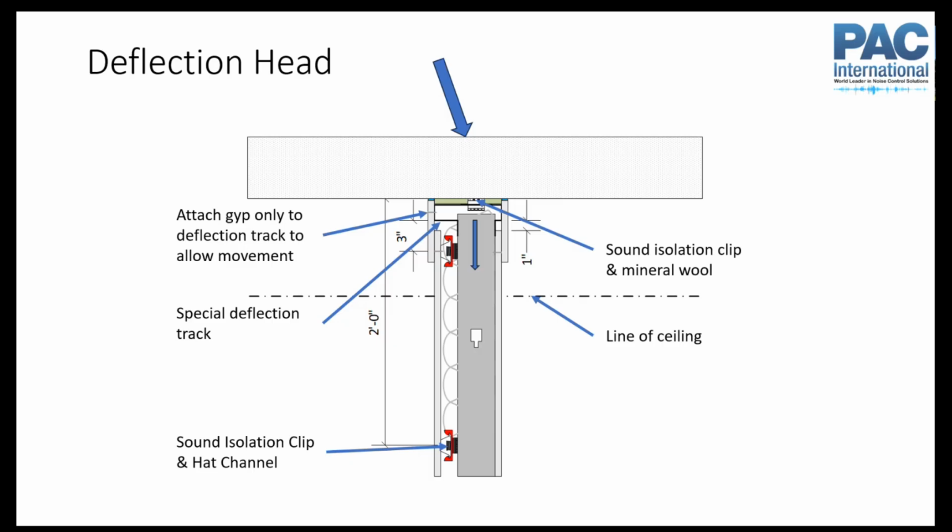But then we also need to think about this path from the floor ceiling structure down into the wall. And say, we've got a continuous concrete slab or maybe a continuous CLT, like mass timber panel, right? And as people are walking on that, we've got this impact sound, this impact energy that's in this structural element up above. And if we have a rigid connection between our wall and that floor ceiling assembly, that impact sound that's in the floor up here will get transmitted into this wall. And if we have something really rigid like concrete and then steel studs, and we have a very rigid connection between those, a lot of that energy can get through that. And you'd be surprised how much of this sound can get transmitted through a building.